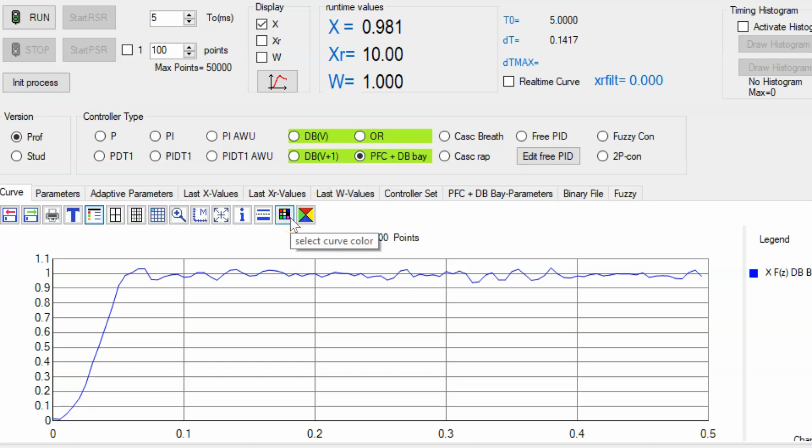So this is a big disadvantage of the deadbeat controller solution, independent of whether this is the original one or my special one. So we need a different design, and this comes now with my presentation of the PFC, the predictive functional control, as this controller is called.